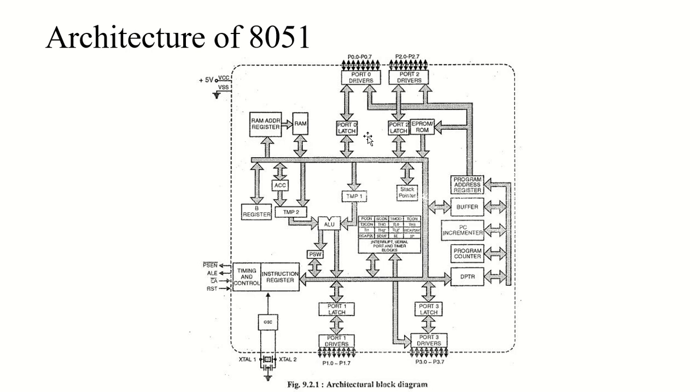So although the microcontroller is a 40-pin chip, it is appearing to have 64 pins. As two functions are multiplexed, in order to decide which function is supported, we need to see how the circuit is connected, and what software commands are used to program the pins.